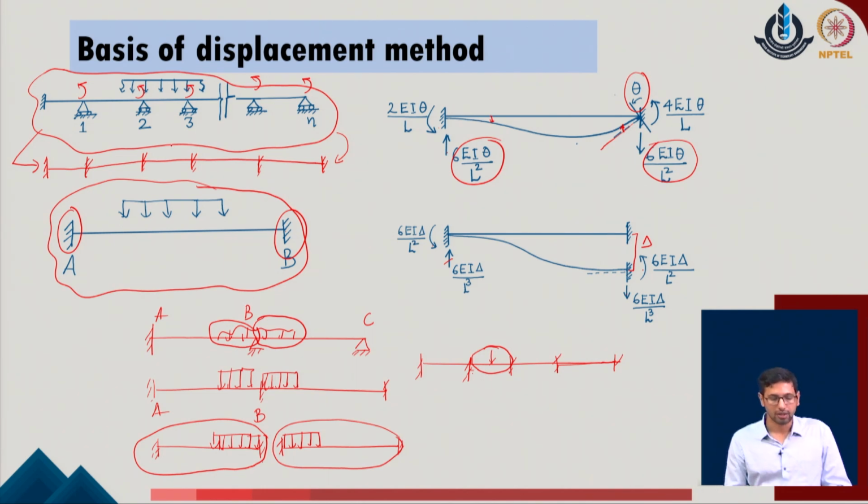What we have summarized over here is that a kinematically determinate system is a unique system for a given problem. Any of the load which is active on the given system can only have the influence on the given span on which it is active in a kinematically determinate system. Any of the load which will appear at the joints of the given problem will not influence any of the support or any of the members of the given system other than the support at which it is active.